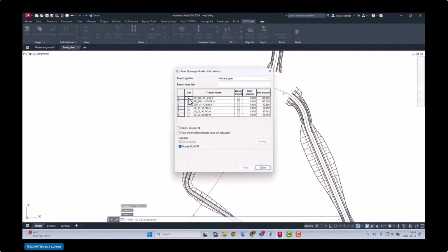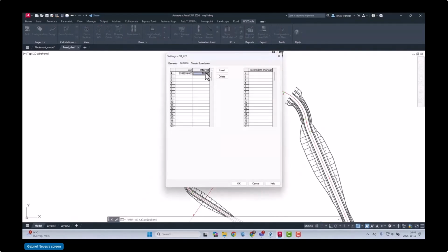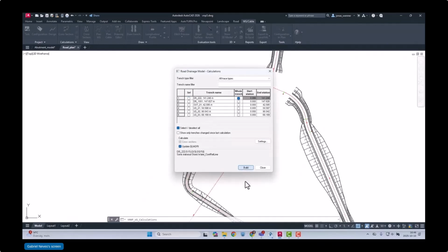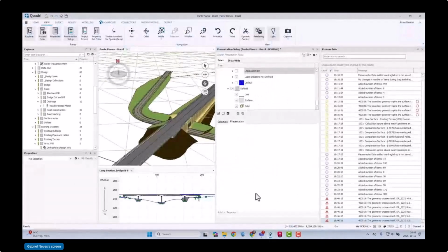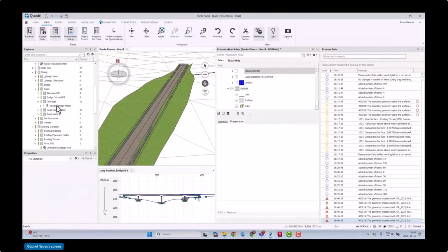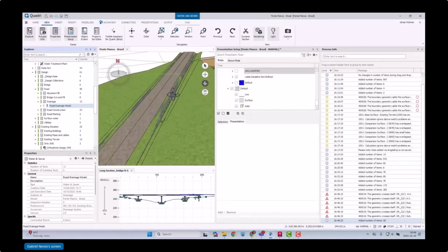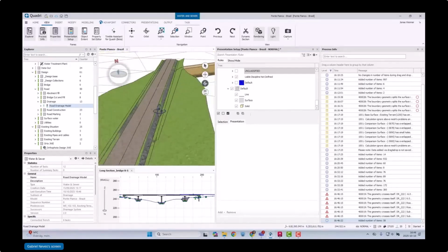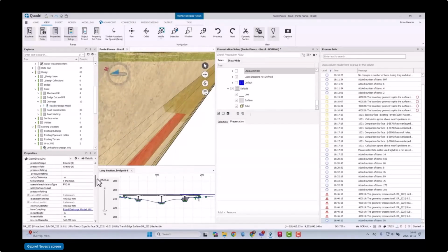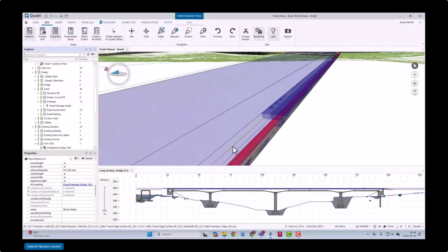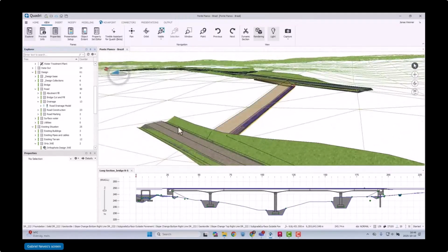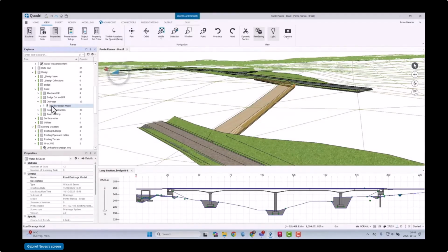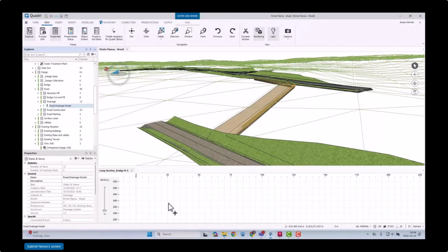And you also see here now when we just make some calculation of the trench, and then we wait for it to be stored back into the Quadri model. There we can just drag it onto our view, and then we see our manholes there with the drainage pipes and so on. And of course, we could send this also as reference data to the Tekla model to use it as input data for the bridge design as well. So it works more or less in the same way as when you use the road as input data to Tekla. You can also use the trench in some ways.